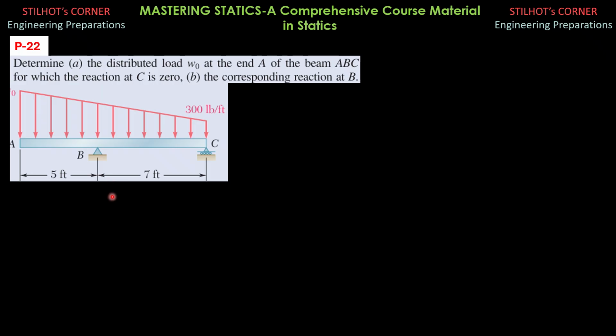So putting the reaction and the division of this loading, I divide this into two triangles as shown, and I'll call this upper triangular line load F1, the equivalent force, and for this lower triangular line load, I call it F2. Then the reactions, we have 0 at C, By, and Bx as shown. So since there's no other horizontal load, we can therefore say that Bx is 0, summation of forces x 0. So Bx plus nothing equals 0. So Bx is 0.